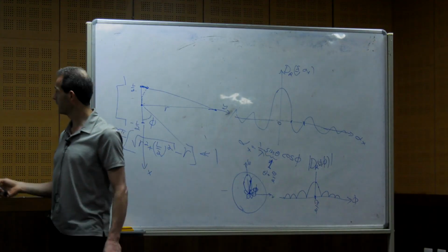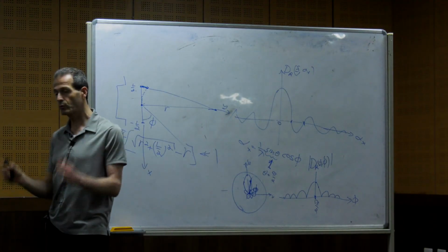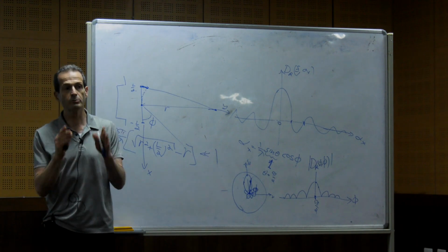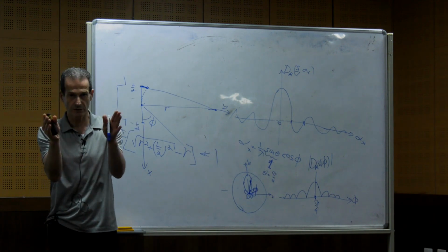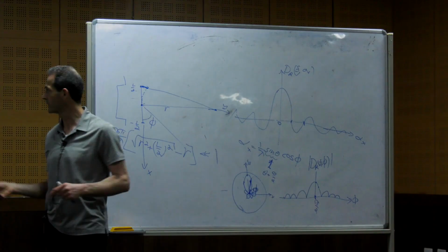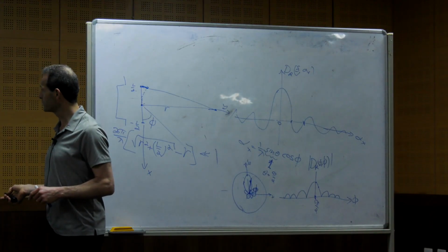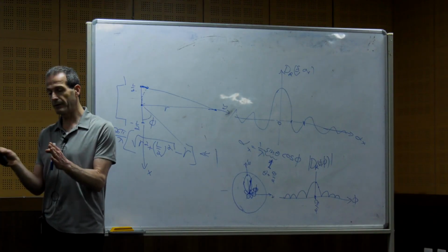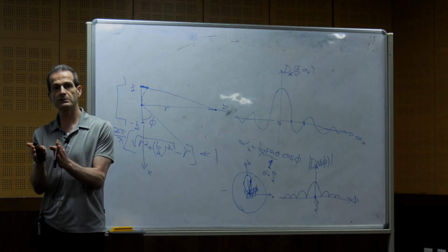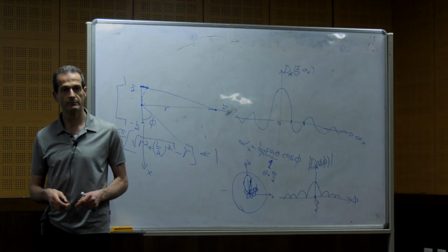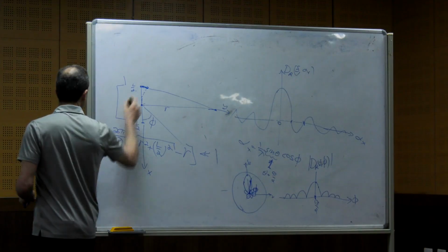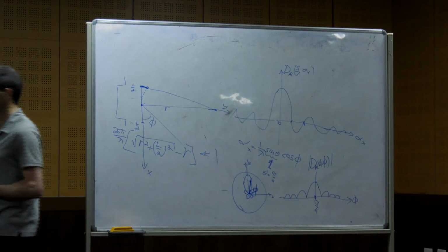We want to measure a signal that comes from a certain direction with a certain beam width. So if the frequency is high, the beam width becomes more and more narrow. This is the response of even such a simple aperture.